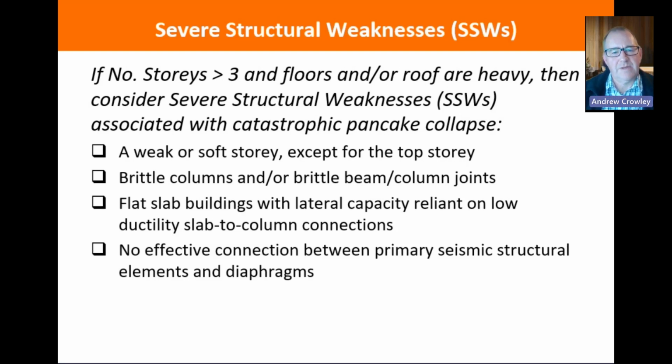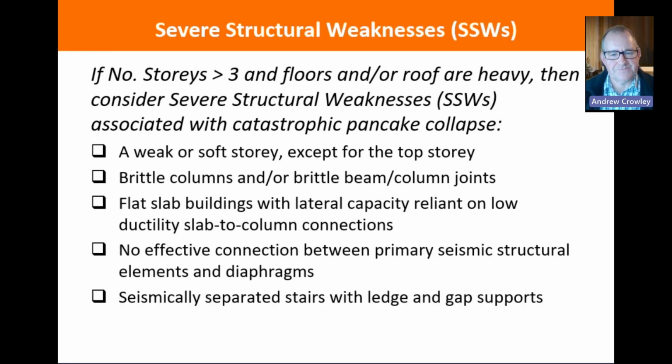And if you've got a diaphragm, is there an effective connection between your diaphragm and the other lateral load resisting elements? And if you go over 6 stories, now they only put this for the taller buildings, based on the idea that the taller the building you have, the more likely the spread of the gap between your stairs and the supporting structure is going to be large enough to dislodge the stair.